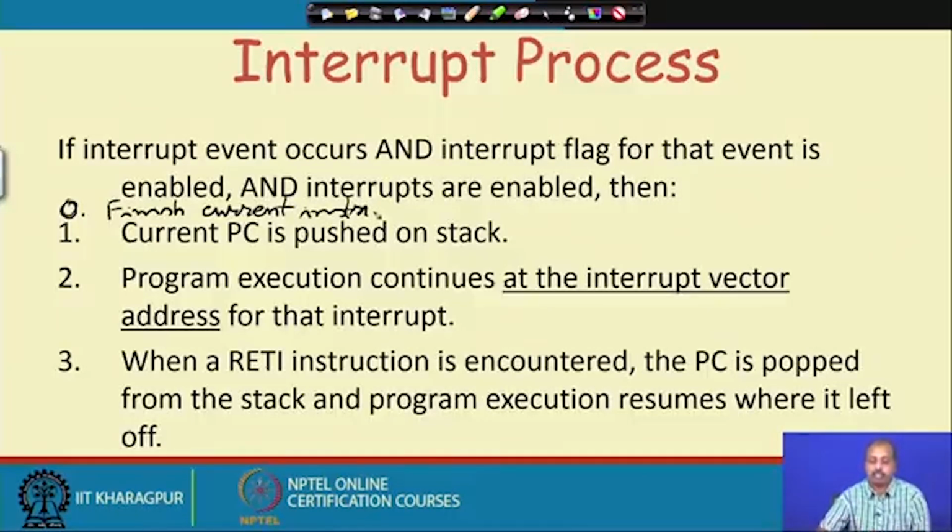routine. So, after finishing the current instruction, it will save the program counter value into the stack, and the program execution will continue at the interrupt vector address for that interrupt. In case of 8051 all the interrupts are vectored interrupts. There is nothing like the non-vectored interrupt INTR that we had in 8085. Here all the interrupts are vectored interrupts, so their addresses are fixed.